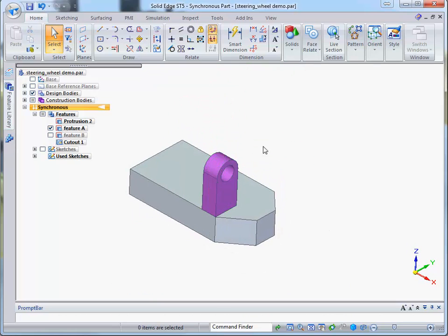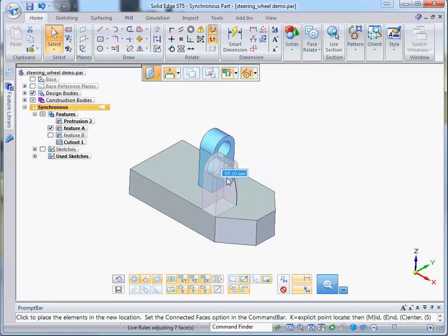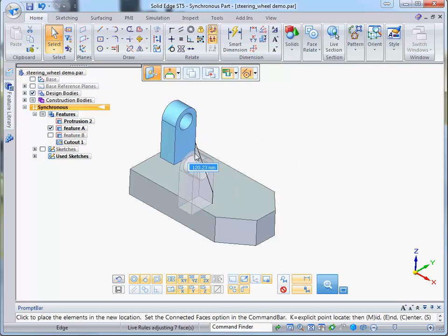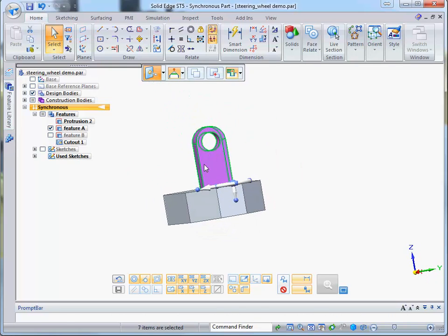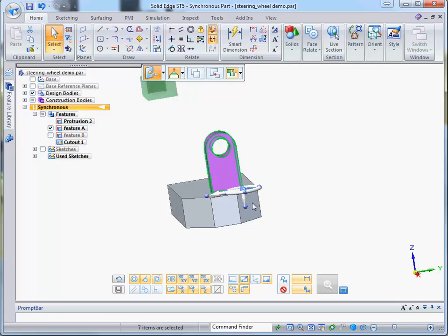Okay, so say I wanted to move it around on that 2D face. Again, select it all, move my steering wheel down to the top face, and then click on the blue plane that's within the torus. That allows me to move around in 2D space, like so. Gives me free movement in 2D.